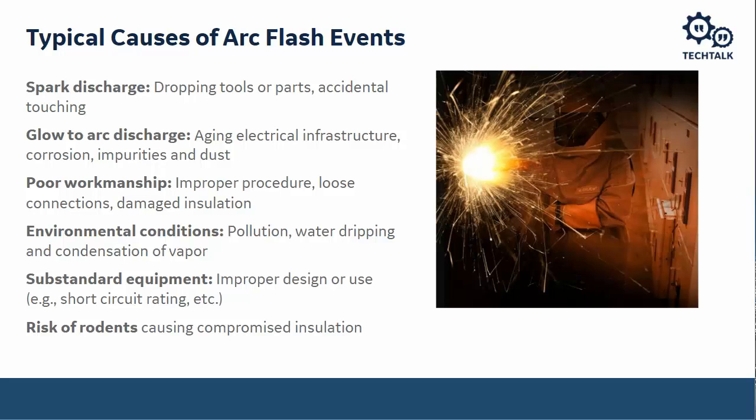I was doing commissioning in a live substation. This particular circuit was energized, but I went to check a CT circuit, and the ring lugs weren't crimped. The wire was just in the sleeve. It missed crimping altogether. So you can have loose connections that can grow and cause these arcs. Environmental conditions, such as pollution in your environment, gases, and contamination blowing around, can also create an arc.